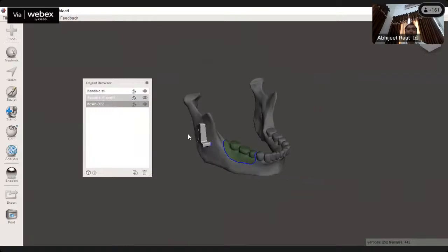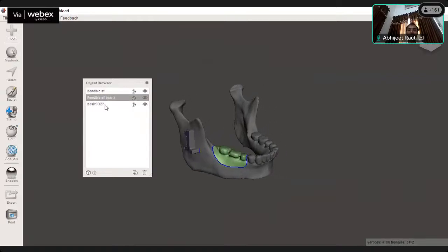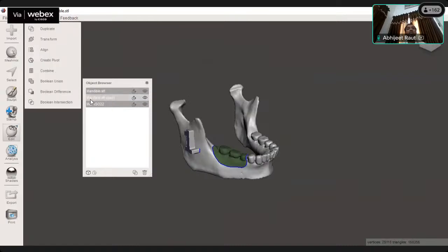It is not a meaningful geometry to show you the reduce command, means the Boolean operation for subtraction, but still, if you would like to remove that one, take the example of another shape. If you would like to remove that particular area from that other body, you just need to select that entity and then the other entity, then you can see the Boolean operation or other operations will appear.